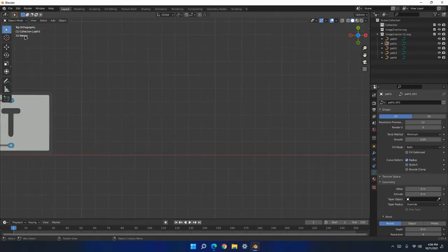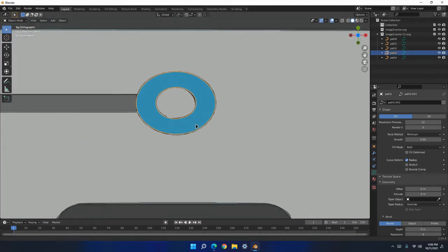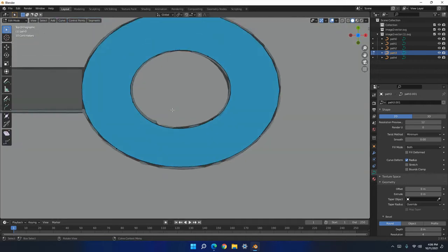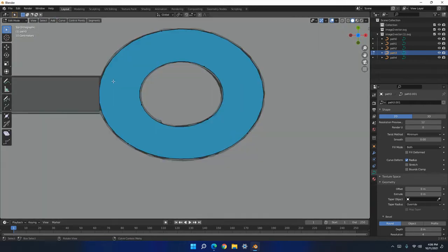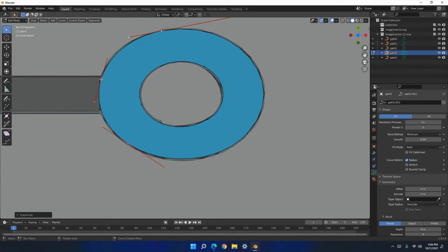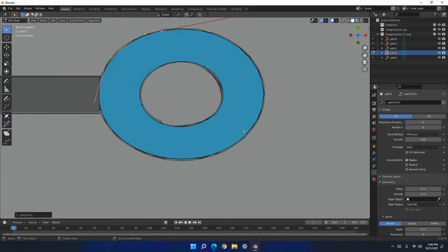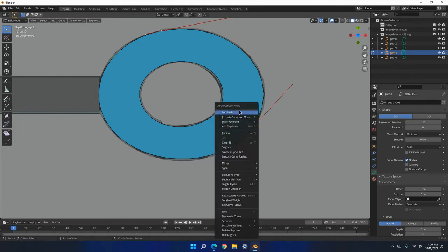If your logo has circles, then it may be a bit hard because the circles are not exactly a circle. It is very jagged, and you'll have to edit that a lot. To fix it, just select both of these, right click, and click subdivide, and then you'll make another joint in the center. You want to make this aligned, and then that's basically it. You just want to add as many subdivides until it is kind of HD. But for this corner, as you can see, there's no points in between this, so I'll want to make